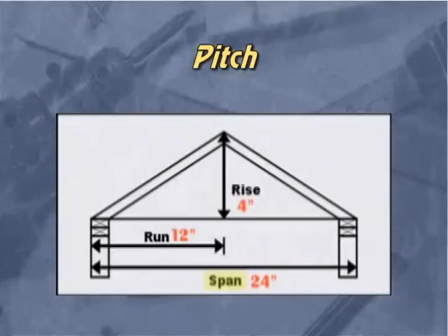Let's go on to nails. Nails are coarse fasteners, and they come in many shapes and sizes. The thing we need you to know is basically in this second paragraph where it begins, penny sizes. That's in the middle of the paragraph there. Let's highlight. Penny sizes are denoted by a D, such as 6D or 5D, which specify the nail gauge or thickness and its length.